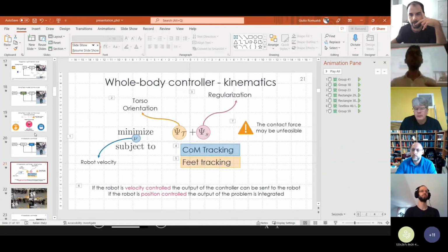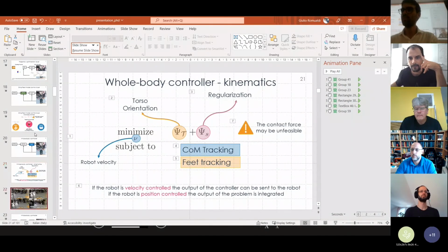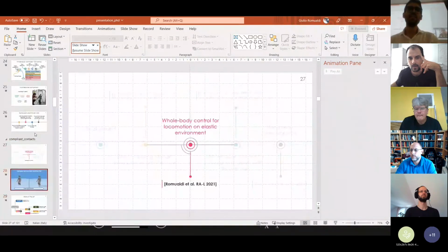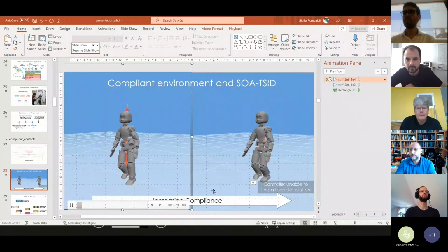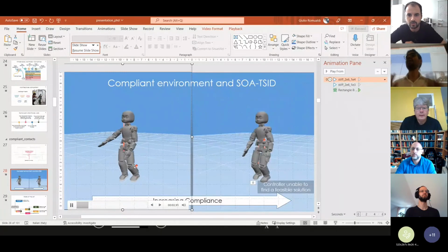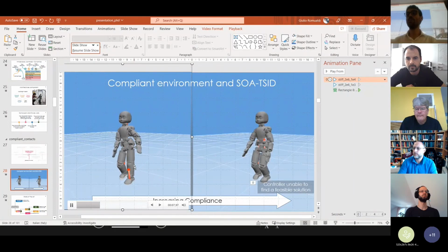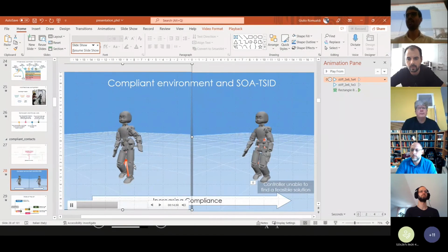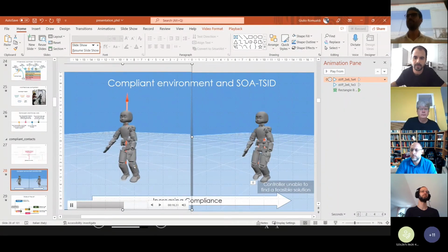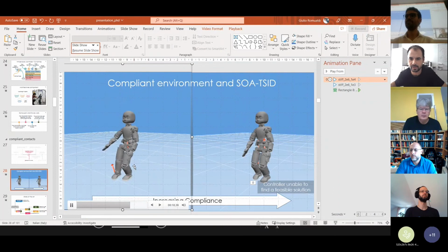Actually, we perform our own simulation, so we designed our simulator. And where do you close the loop? Where does the floating base position and motion come from? That's true. So we assume that we can directly control the torque, and the floating base is given as a sort of ground truth. We don't have any kind of floating base estimator here, and low-level joint torque control. Okay, thanks. I'm handing over to Jerry.